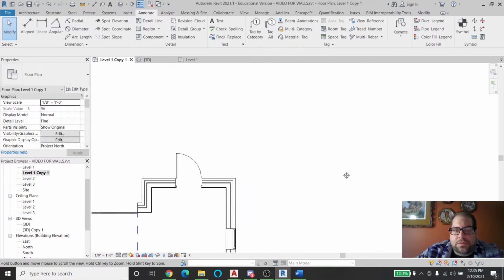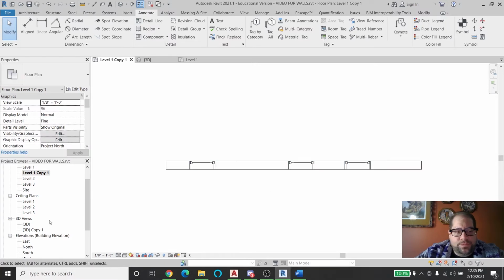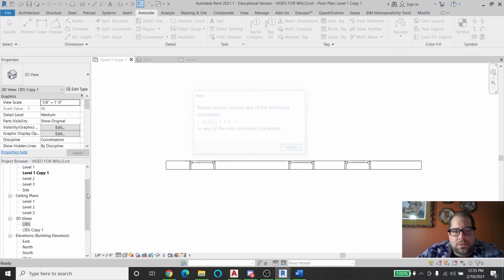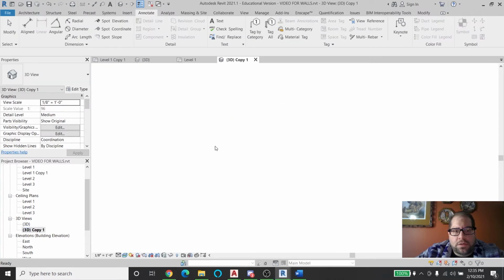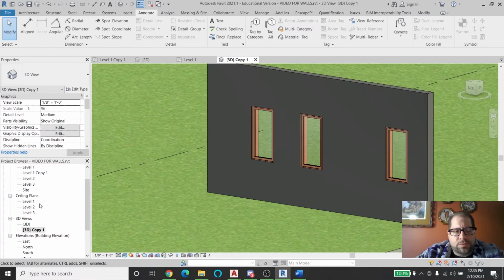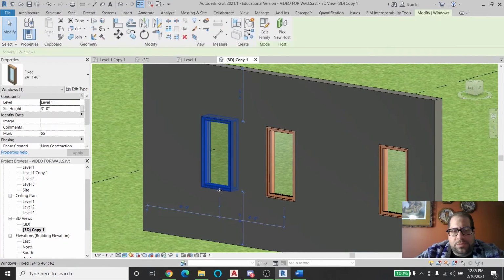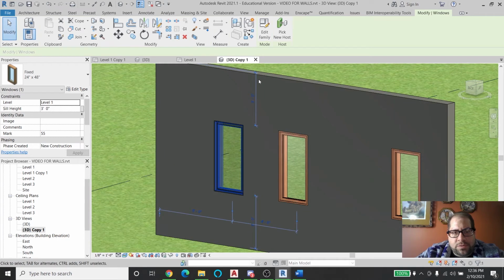Let's take a look over here at this temporary wall I had made with 3 windows. This is what it looks like in 3D. Okay, so I'm about to modify those windows. In 3D, if I click them, you'll be surprised that witness lines don't just exist in 2D. If I wanted to actually change the height of this window in reference to the height of the wall, I can do that too. I could just make it maybe 1 foot away from the wall, and it will go